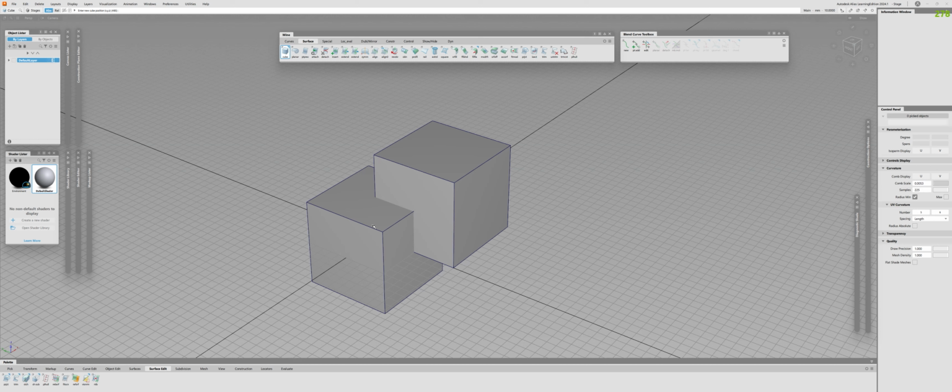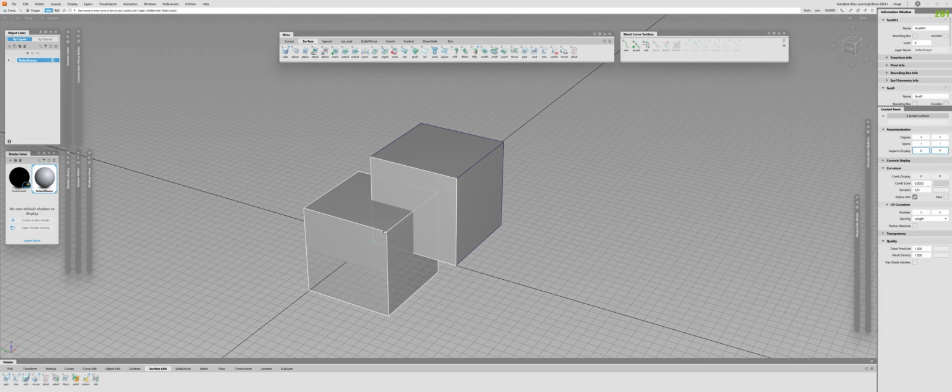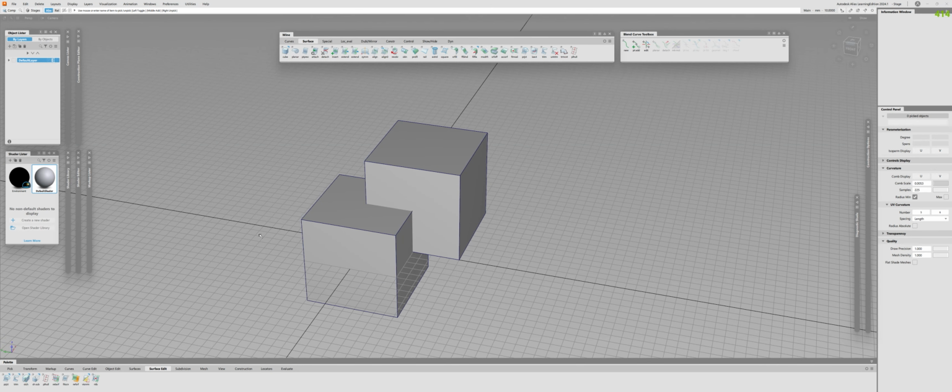Now, there is one caveat with Boolean operations. They will not work on surfaces. So basically, you won't be able to run a Boolean operation on these cubes unless you convert them to a stitched version of themselves. We have a specific operation called stitching, and we use this to transfer data to downstream CAD software, or to quickly check positional continuity, that the objects are actually solids and don't have any holes within the tolerances we're building with. And another reason is just to perform the Boolean operation.